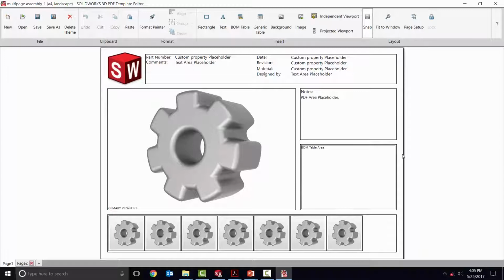So whatever information you need downstream, whether it be manufacturing notes, materials required, dates, revisions, all of that information is going to be captured inside of the published content rather than having to capture that as a secondary file on a 2D drawing. So that was just a quick glimpse of how the standards and templates are developed and how you can create a standardized template that ensures you're using the same repeatable data every time downstream.